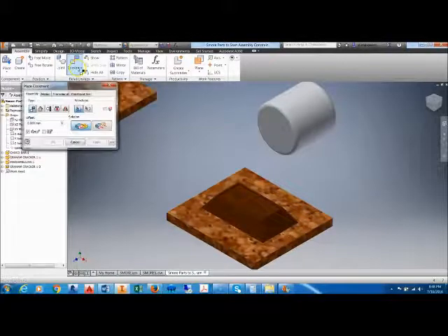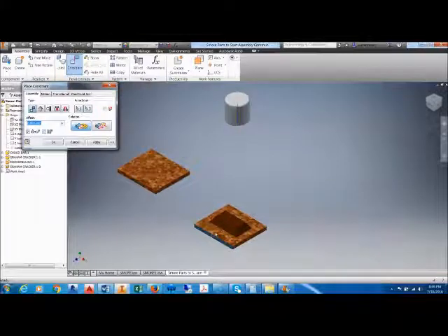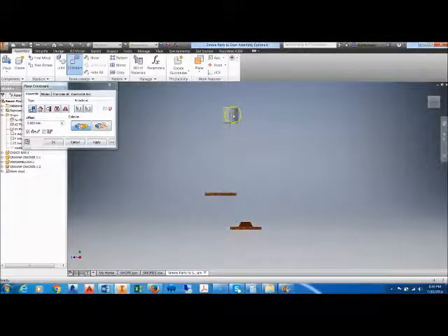I will grab my constraint tool, using again the mate and the mate tool, and I'm going to grab the axis. So I grab the axis, and I'm going to come and again grab a face. And by doing so, I'll zoom out so we can see the marshmallow has constrained itself through the center axis to the outside edge. Now I'll turn the entire assembly so you can see that we may be very far away, but we are still in plane.